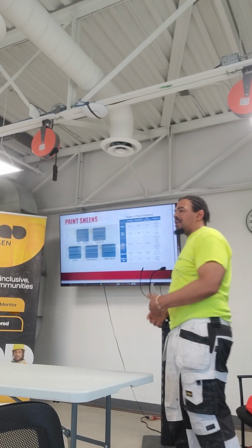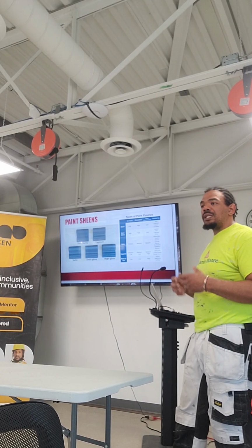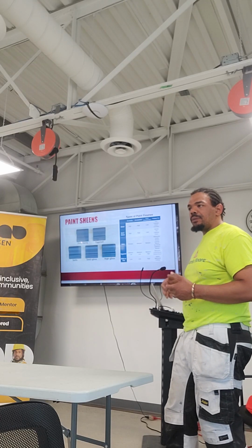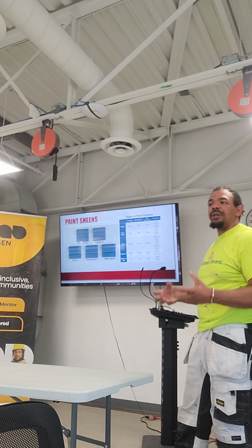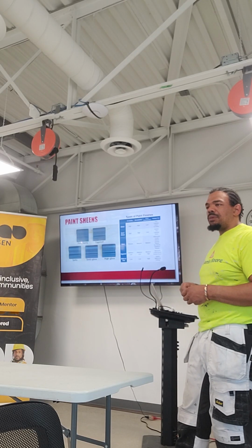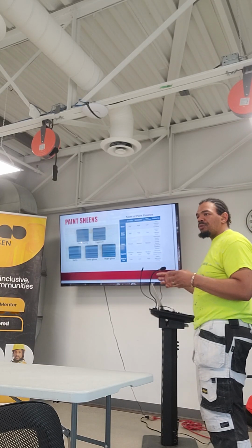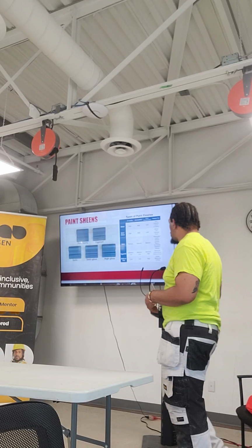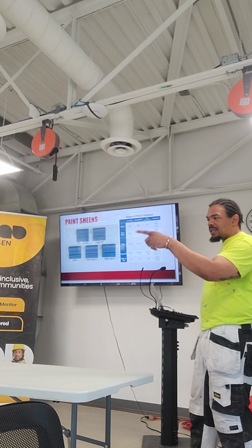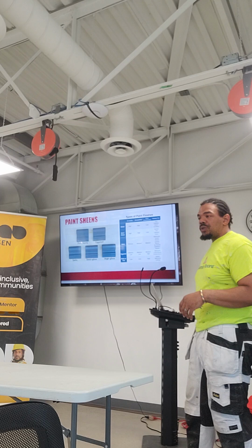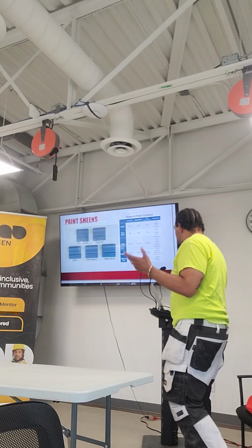At this stage now, in decorating on the residential side, we're seeing a lot more requests for satin on doors and door frames and baseboards and window frames, as opposed to semi-gloss, because people think semi-gloss is a bit too shiny now. So they want something that shimmers and is not so shiny. So satin has more of a shimmering or a glowing effect. So it works very well on the same kind of cabinetry and millwork as a semi-gloss. So that material there is a 20 sheen, so that's like a satin. If we went a little bit higher in degree, it would be a semi-gloss. It would be a lot shinier. But even still, that's pretty shiny.